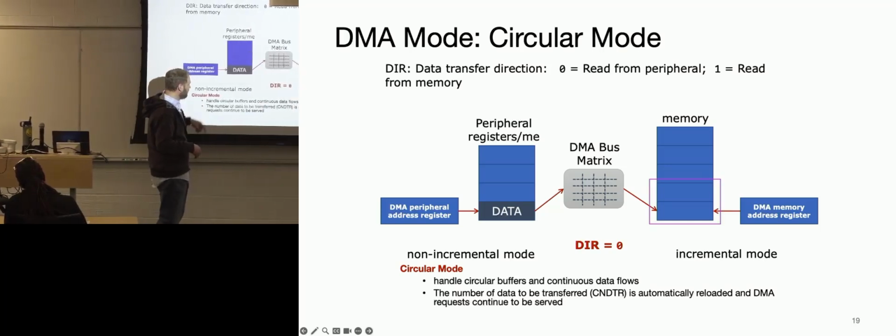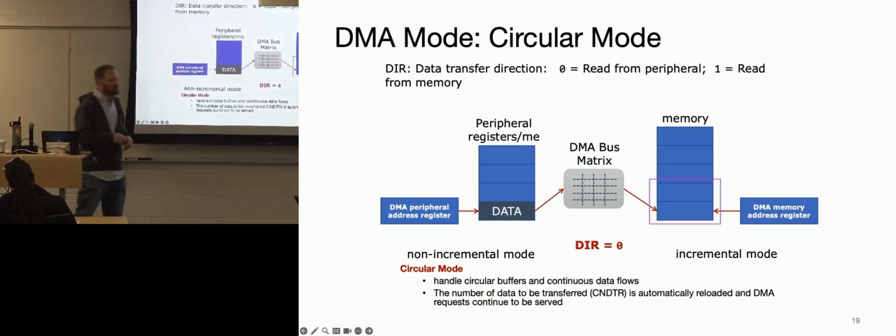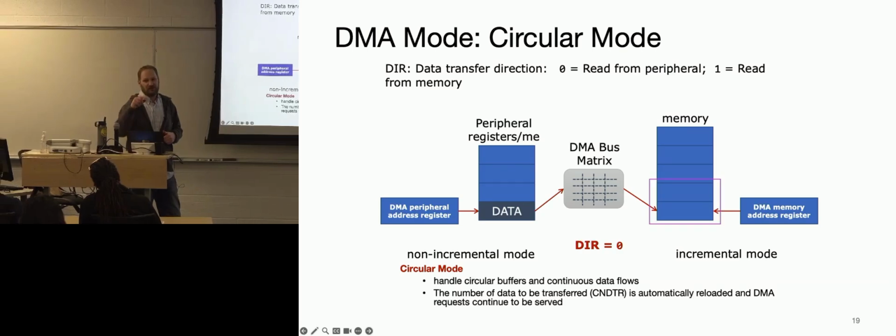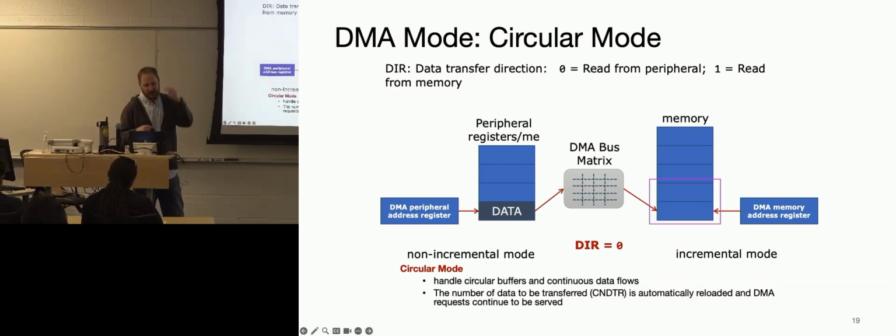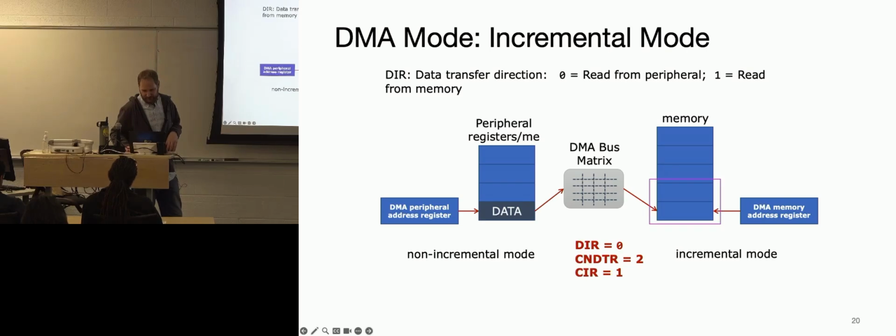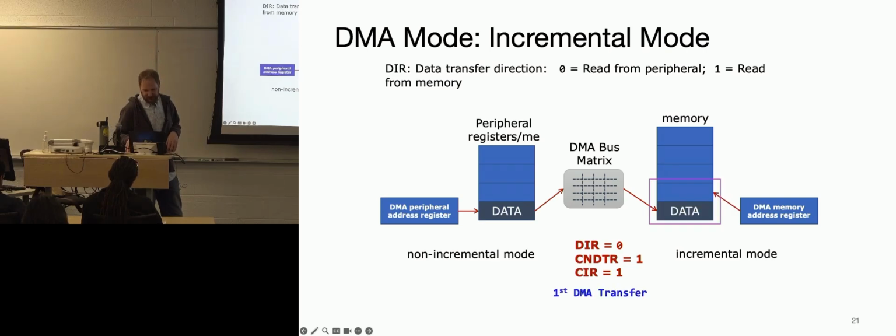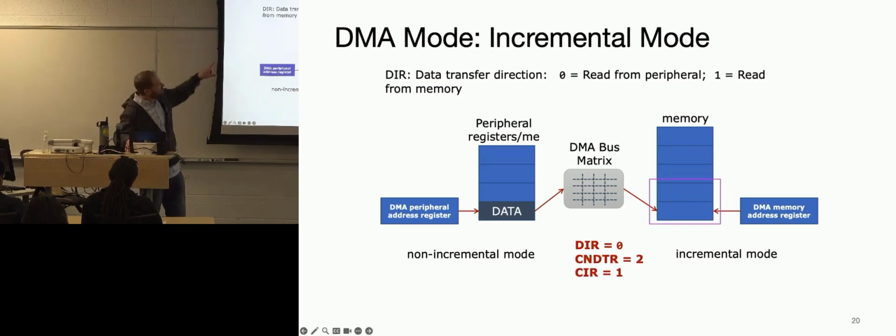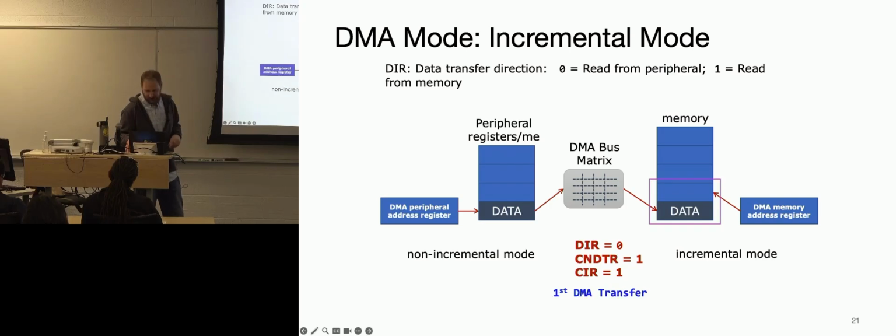And so there's a bunch of extra flags you can look through to show you, okay, here I'm halfway through, like you'll get pointers to show you where you are on the circular buffer, so that your core can wake up and make sure that it's pulling data out from the correct place at the correct time. I think the labels just got mixed up, but I'll make sure they're updated and put out in the slides.